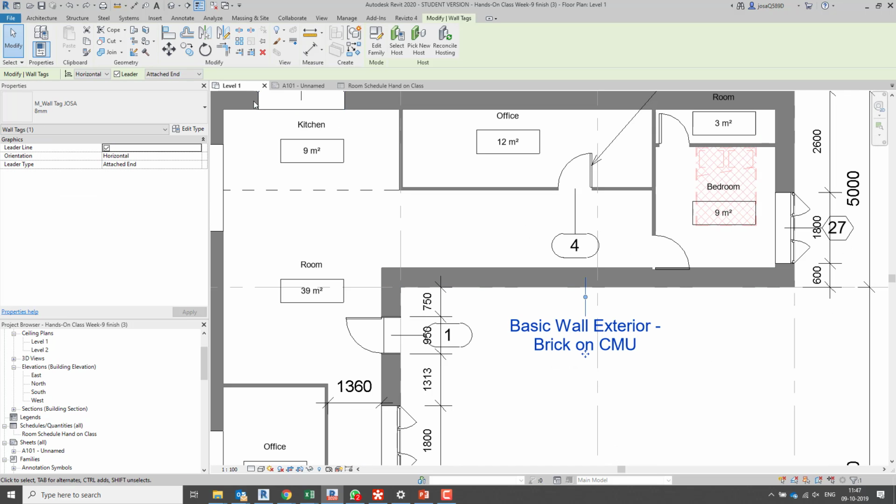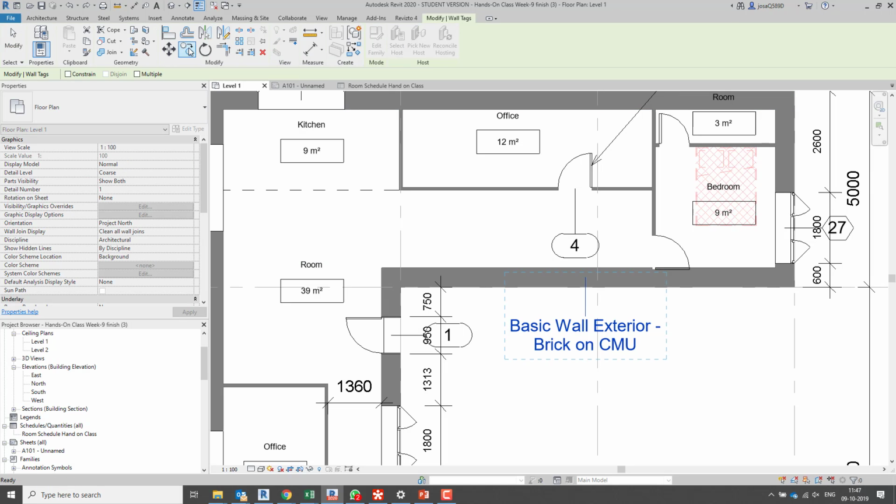So, come here to the top, copy. Because now, if I do this copy, if you see the prompt, it tells me, oh, actually it's doing the extension. Okay. If I select copy, it tells me here, click to enter move start point.